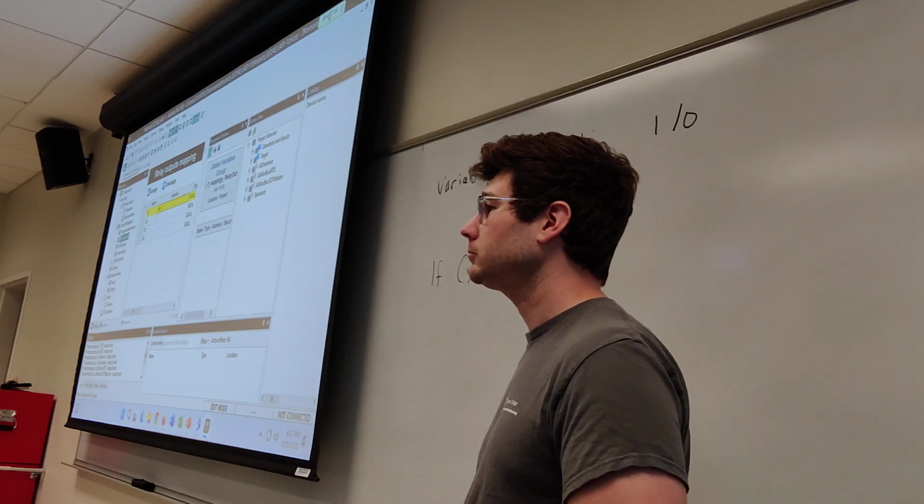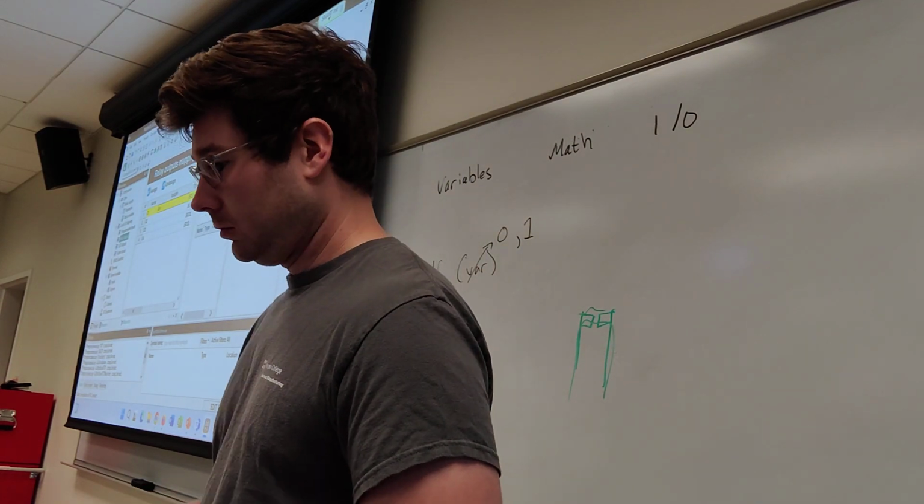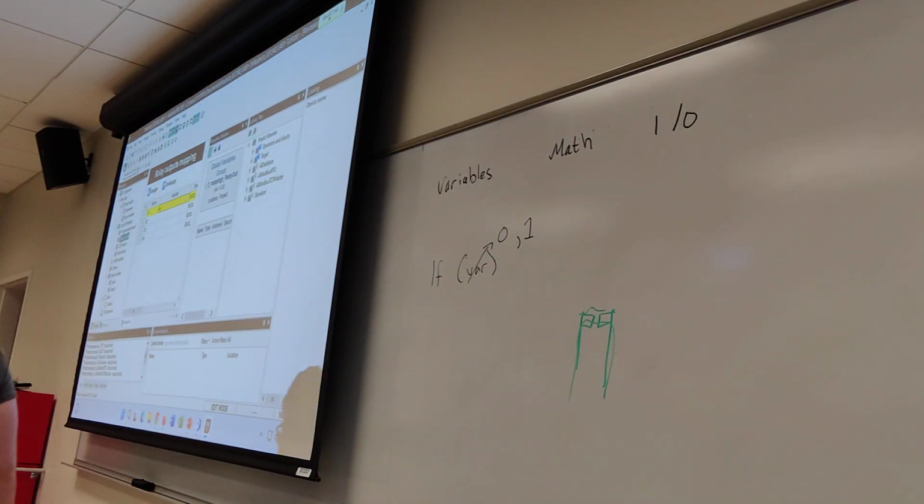Would you mind showing me how you would connect to your Arduino again? That error code, trying to connect to it? Sure. Let me get you sorted. The software can be finicky sometimes. And you were saying something about setting up communication. Go to Modbus properties. Change your port from COM1 to COM9. It'll be a 50-50 shot whether it's 8 or 9. Or PLC. And then, oh, there we go. Good stuff.